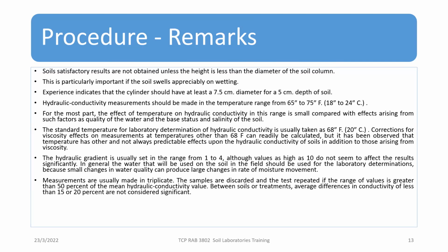Therefore, correction for the viscosity effect on measurements at temperatures other than 18 can readily be calculated, but it has been observed that temperature has other and not always predictable effects on the hydraulic conductivity of soil, in addition to those arising from viscosity. Here is more emphasis on the impact of temperature on hydraulic conductivity.